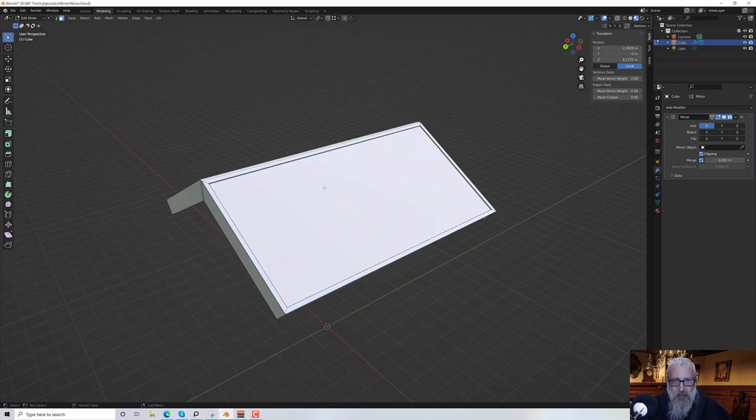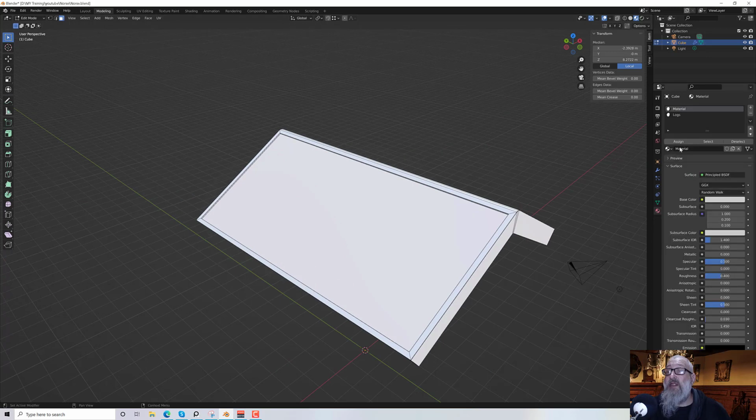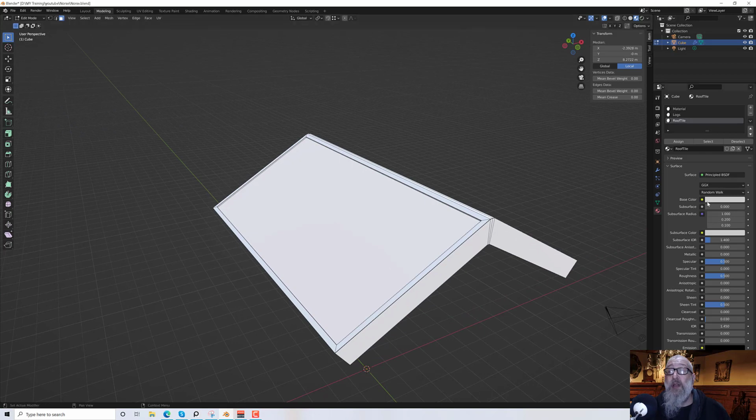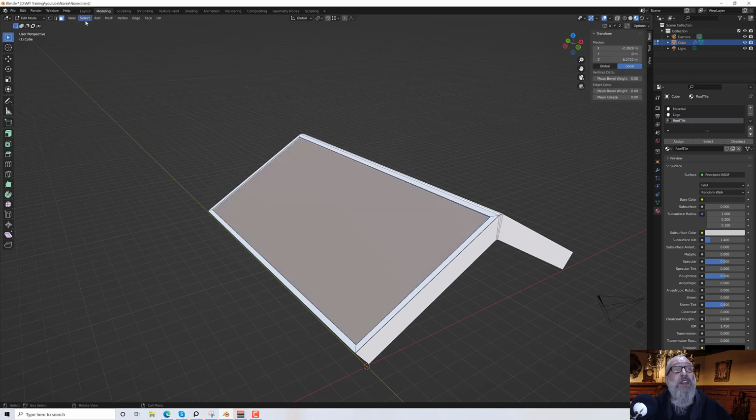And because I know I'm going to call that, make a zone for that one, we'll go down to materials now, we'll add a new zone and then call it tiles, or roof tiles, just in case we have any tiles elsewhere, and then assign it to that polygon. Let's give it a colour so we know what it's done, or in this case a grey. And then I want to select and invert.